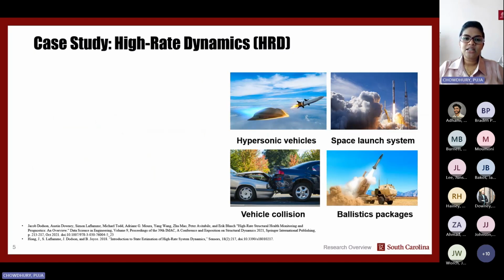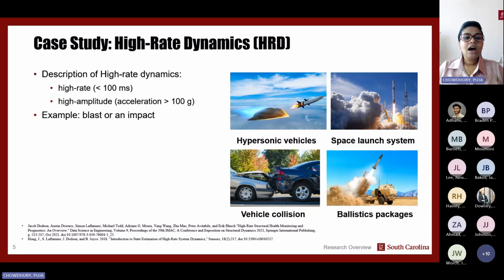For the case study, the important thing is the high rate dynamics. So we need to know what this high rate dynamics is. High rate dynamics are described as a dynamic response from a high rate, which is less than 100 milliseconds, and a high amplitude, which is more than 100 G acceleration.